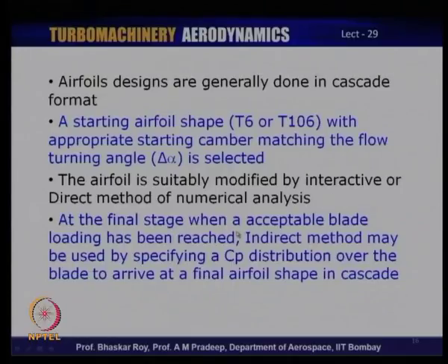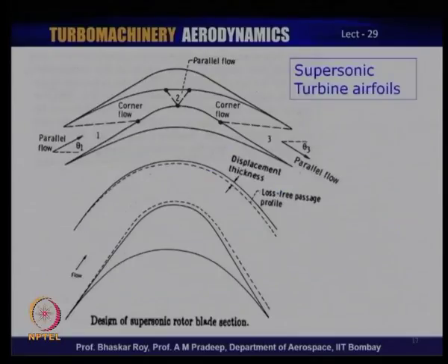However, there is an indirect method which is normally adopted towards the end of the design, when you have a reasonable idea what would be the CP distribution over the blade by the earlier iterative or interactive method, and then you feed that final desired CP distribution and adopt an indirect method of creating your blade profile, in which case the blade loading is already decided upon, and then you get the final profile from the indirect method of CFD analysis.